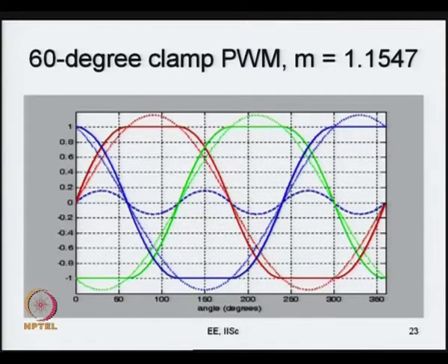The other advantage you can get is, of course, that you are not switching for one third of the cycle. Therefore the switching loss can be reduced. As for the conduction loss, here you see the positive device will get heated more because of continuous conduction. In the same way, the bottom device in that R phase leg will conduct continuously and get heated up. So they get heated to an equal extent if you look over a fundamental cycle. So it is distributed. Here the assumption is that the line cycle is much shorter than the thermal time constant.